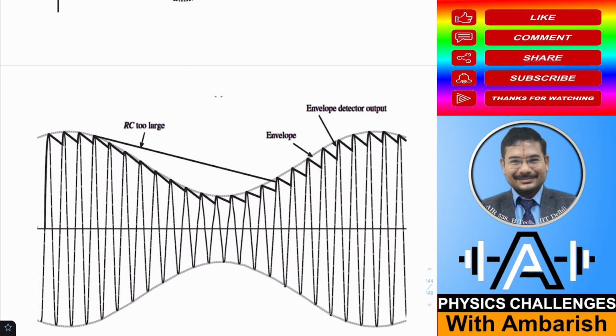So we need to have RC in the Goldilocks zone. RC cannot be very small, and RC cannot be very large. In both cases, we will not be able to accurately reproduce the envelope. So what we really want is RC should be just sufficient so that I am able to approximate this envelope as well as possible. Okay.